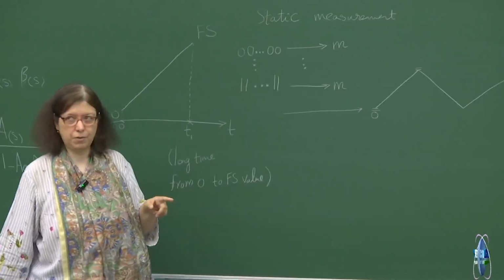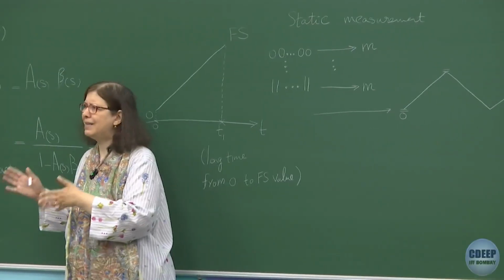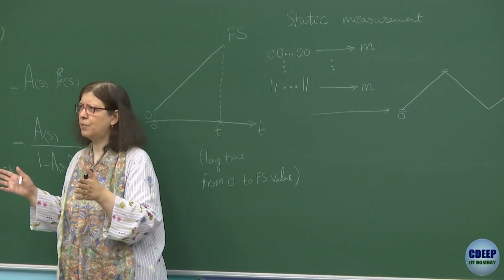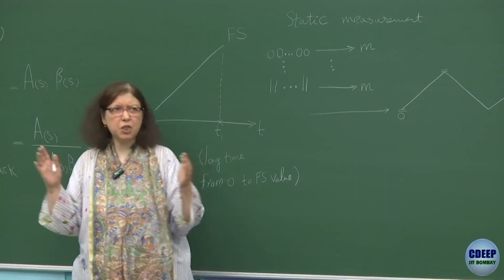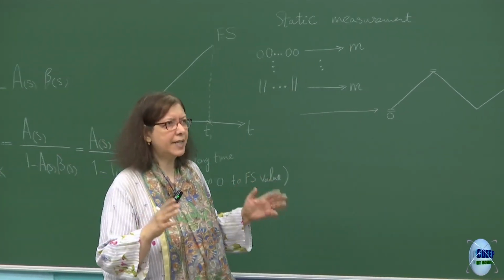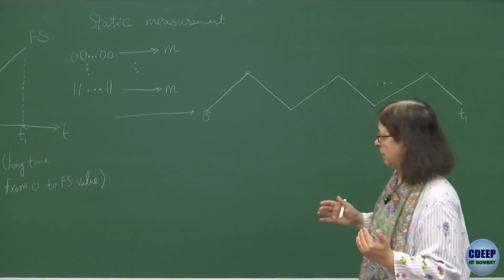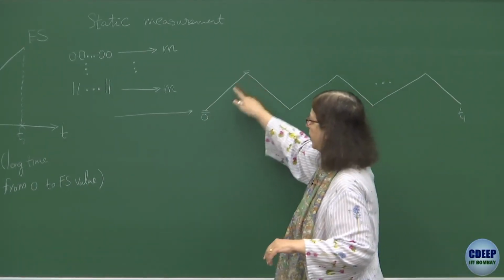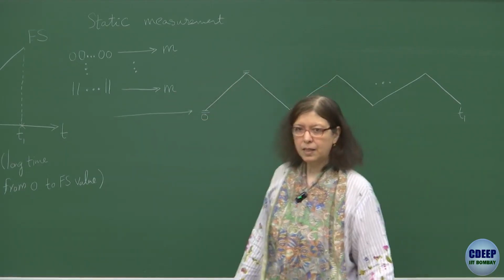Therefore, because of these conditions, more often we are not so worried about the all zeros and all ones code, because we know that all zeros and all ones can be separately checked as a single input, just a DC input, for example. And then depending on the shift, we correct for the gain error and offset error, as we discussed before. Therefore, we are not so worried about these two boundary values. We look at other codes in between. So this is the way.